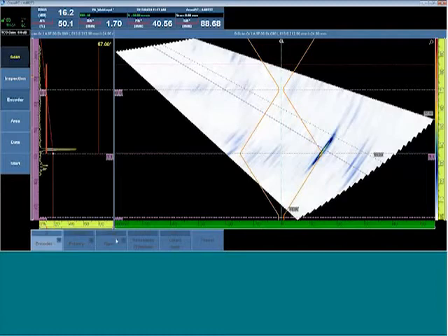The hardware type of encoder: the overwhelming majority of them on the market now are quadrature encoders. There are several other types. The resolution in this case is 13 steps per millimeter. That means when the wheel of the encoder is moving and generating the clock trigger, every 13 triggers equates to 1 millimeter, so that the software can keep track of the scan axes and associate the S-scan data and A-scan data to the probe movement.